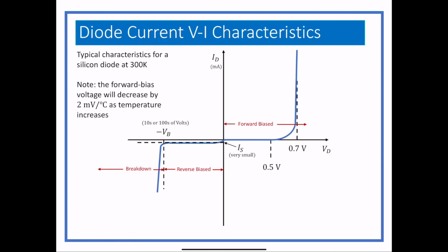It's usually listed in the spec sheet about what reverse voltage you need to break it down. Or you can have devices that are actually designed to do this. You can have Zener diodes, and Zener diodes are designed to cause current to flow at a specific voltage. And usually that voltage is 5 volts, 12 volts, whatever. Yes, and I'm actually talking ahead of myself.